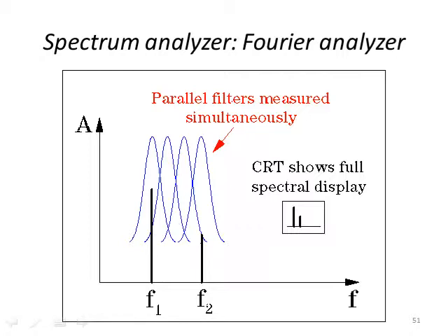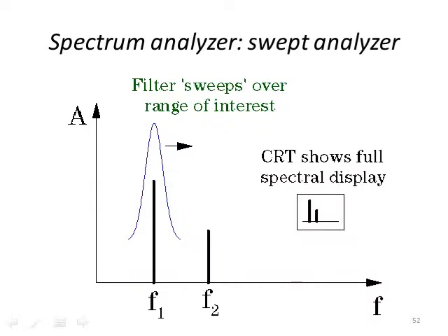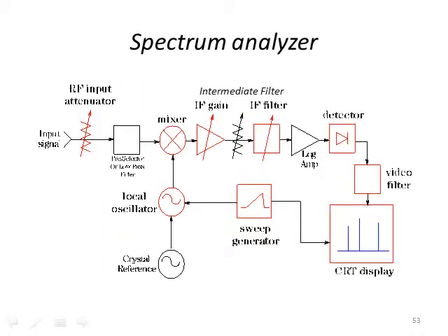Usually this is digital filtering over very small frequency increments over a large range. Now this can also do filter sweeps, where you have one filter and you sweep over the frequency range, and then you can pull out the frequency components of your signal.